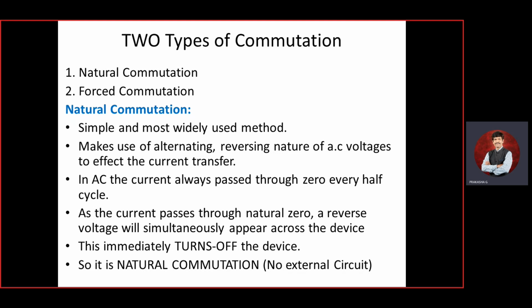That has been elaborated in the paragraph. If a thyristor is on, it naturally cannot go to the 0 or off state. You have to ensure that there is force. In case of DC circuits, clearly it's mentioned, for switching off, the forward current should be forced to be 0 by means of an external circuit.